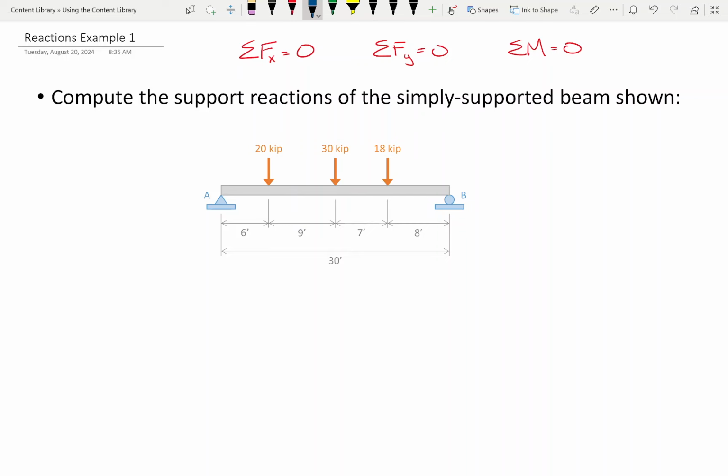So let's start looking at analyzing the structure. What we're going to try and do is determine these support reactions. Now, I'm going to work backwards. I'm going to start off here at the roller at B. We agree that there is one unknown support reaction, okay? And so we're going to start developing a method, and I want to try and be a bit global and universal in how we apply this method, okay? So B has one reaction, and that reaction is vertical in nature because of the way the roller is oriented, right? This reaction could either act upwards or downwards.